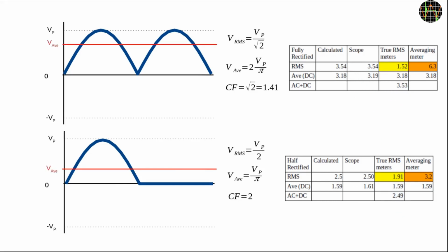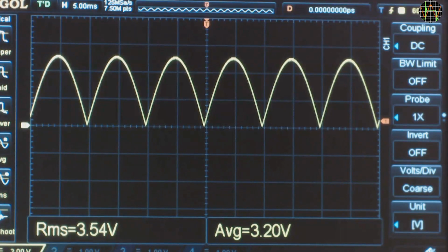What really happens here is that these two waveforms introduce a substantial DC offset, shown here as the red line. But when you switch your meter to measure AC, it is normally using a capacitor in the input to keep any DC parts out. In effect, the whole trace is shifted downwards and the red DC line becomes the new zero line.